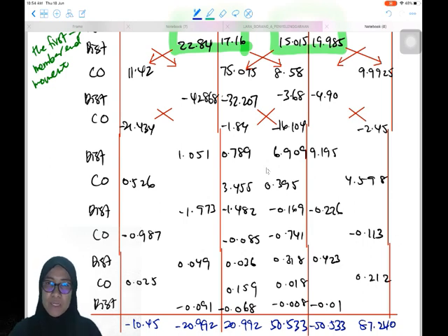This moment can be used straight away to draw the bending moment diagram, because the member end moment is actually the internal moment, and the internal moment is actually the bending moment value. So using this value, we can draw the bending moment diagram straight away.